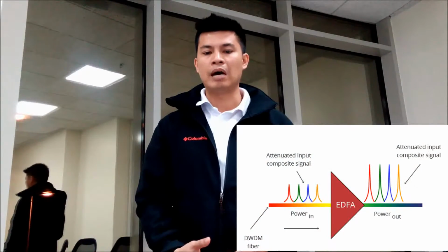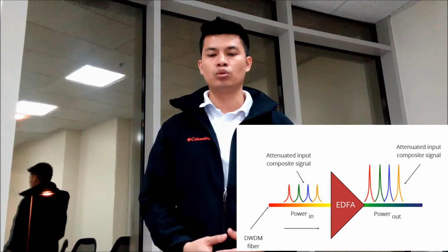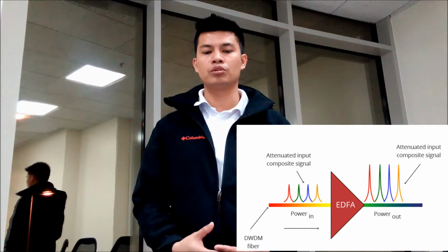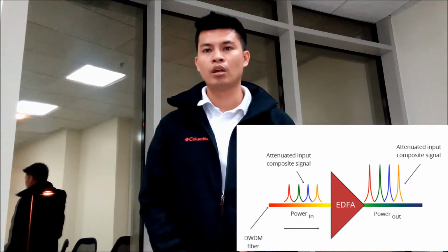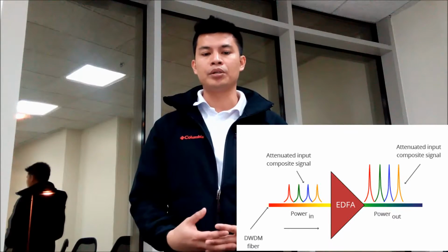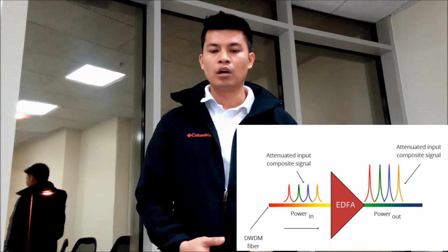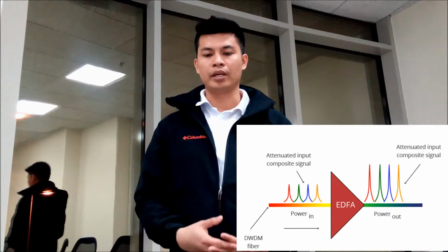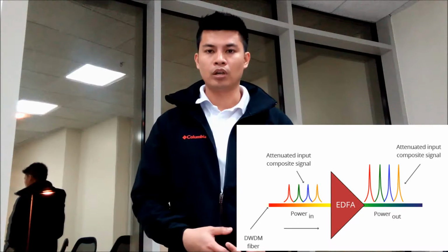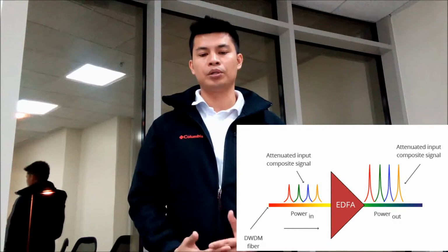Optical amplifiers boost the amplitude or add gain to optical signals passing on a fiber by directly stimulating the photons of the signal with extra energy. They are in-fiber devices, so optical amplifiers amplify optical signals across a broad range of wavelengths. This is very important in the DWDM system application. Erbium doped fiber amplifiers, or EDFAs, are a commonly used type of in-fiber optical amplifiers.